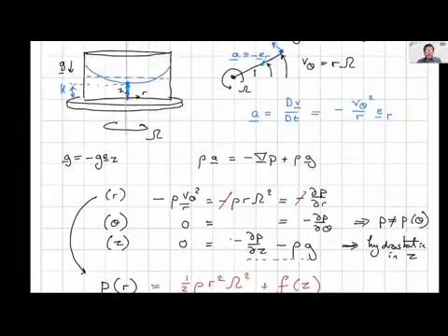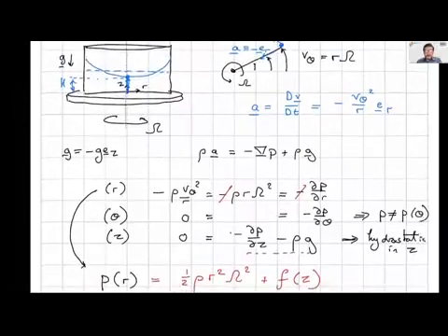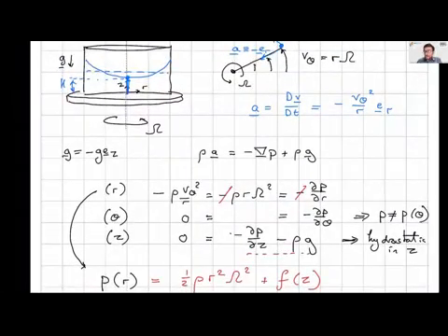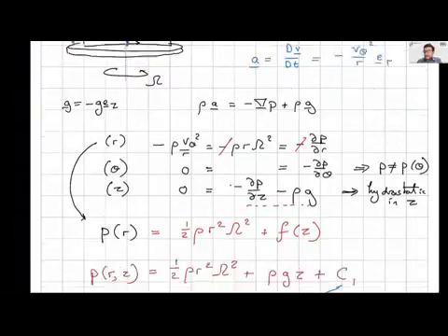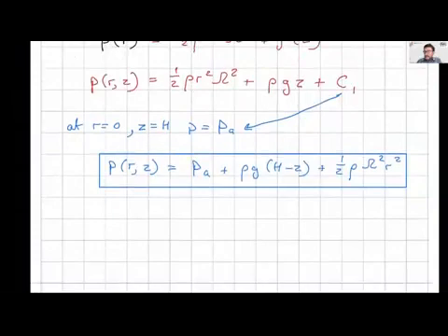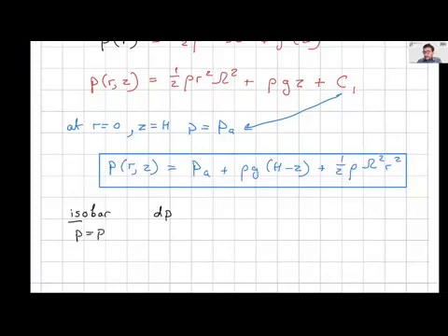So I drew the shape of the surface here. Certainly it looks like it goes like r squared. You can see that as we move out here, the height looks like it's getting bigger and bigger. But the way to really see that is to calculate what we would call an isobar. So what is an isobar? An isobar means a line of constant pressure. One isobar, for example, is where the pressure is equal to atmospheric pressure.